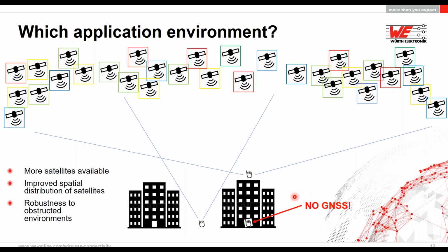As a third example, we consider a receiver which is between these buildings. Now, this receiver will have a limited view of the satellites. In this case, supporting multi-GNSS becomes even more important, because having, for example, a single constellation available for position could lead to the situation where we don't have enough signals to calculate position, because the equations are too few to solve the system, simply explained.